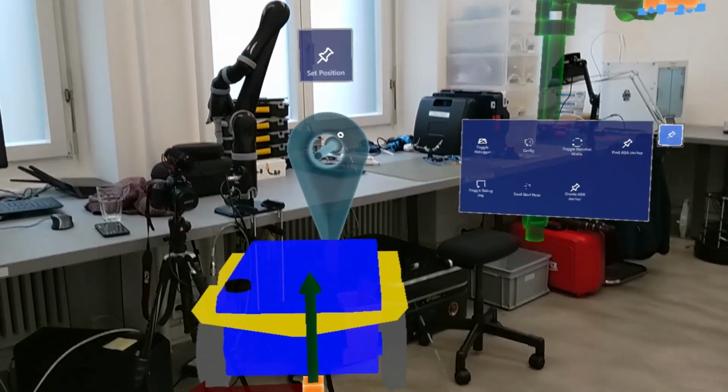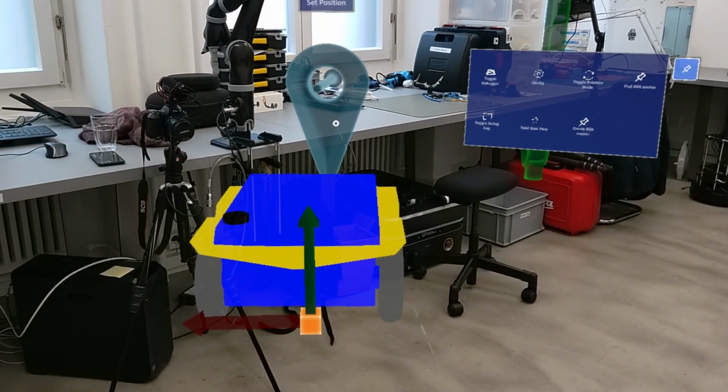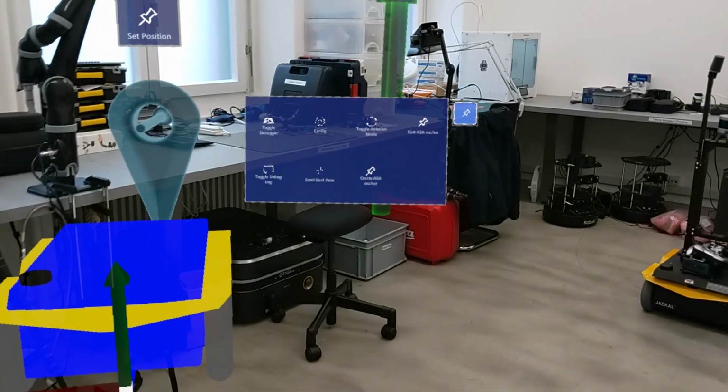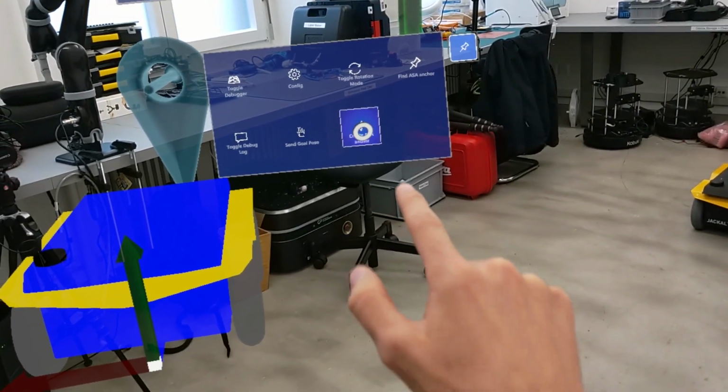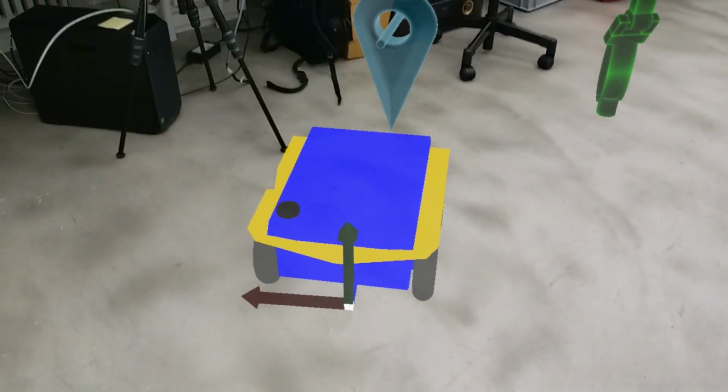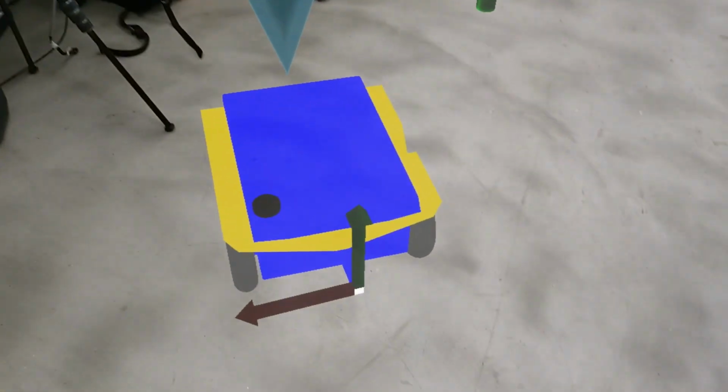First, in order to move the waypoint, let's first create an anchor. To create an anchor, take this orange cube and position it somewhere on the floor. If you have done that, you can look over to the menu and click Create Anchor. As you can see, the Unity app just snapped onto the orange cube and everything is placed there. Also, the anchor ID is saved to the JSON configuration file we just uploaded via the remoting.